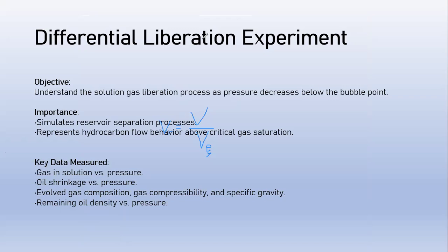The next experiment is the differential liberation experiment. The differential liberation experiment simulates the reservoir depletion to determine the shrinkage of oil, the gas-oil ratio, the density of the fluid, viscosity also.